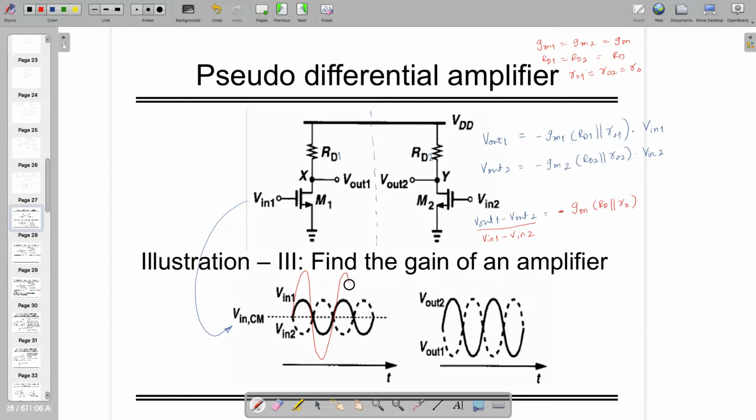so differentially, okay, I need to draw not here, but it will go to 0, something like this, because this common mode goes to 0 and this difference becomes twice, because both of them are 180-degree phase shifted and of course having equal and opposite sign of magnitude, right? So that is what you are going to see here, and there are two outputs you can draw individually. Both will have some output common mode voltage also, which you can call VOCM.